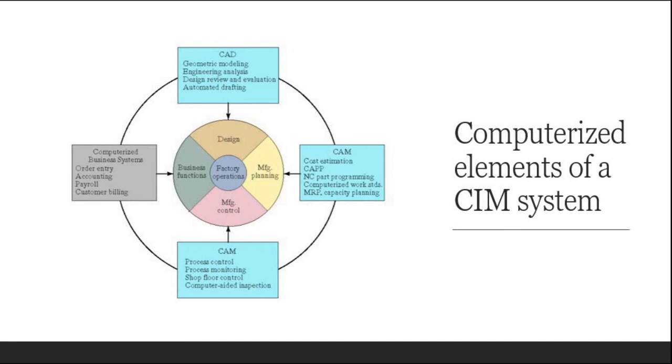The other thing that we will not cover in this lecture is what we call the just-in-time production system. Just-in-time refers to a production system that is organized to deliver exactly the right number of each component to downstream workstations in the manufacturing sequence just at the time when the component is needed. This is basically the pillar of lean production, and this term is usually used not only for production operations but also for supply delivery operations, and also in terms of inventory planning.